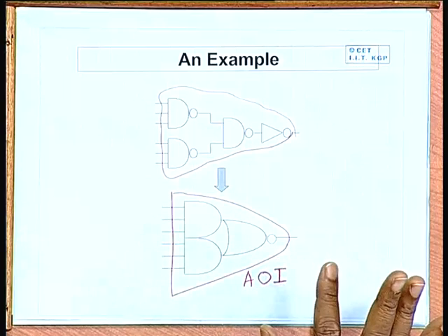So, if you do this, your entire netlist which was there at the beginning will now get transformed into a netlist of cells which have been picked up from the technology library. Now, as I said, there can be overlap among the cells. The objective is to have a minimum number of cells if area is important, or to reduce the number of levels of the cell netlist if delay is more important, and so on. Okay.